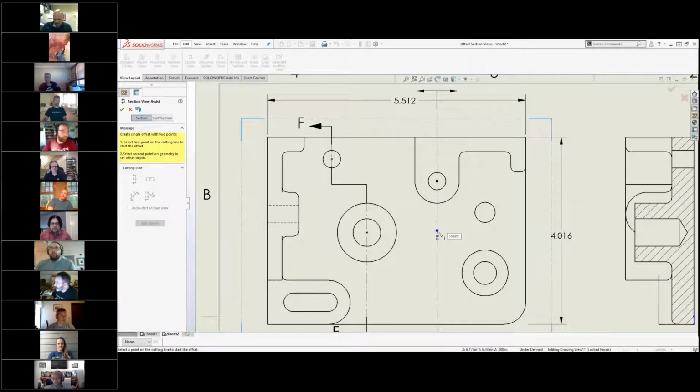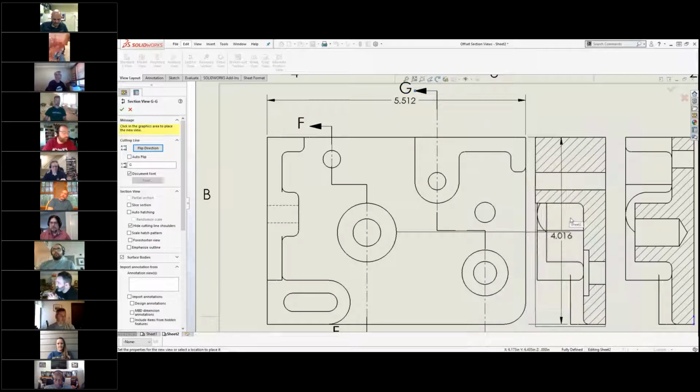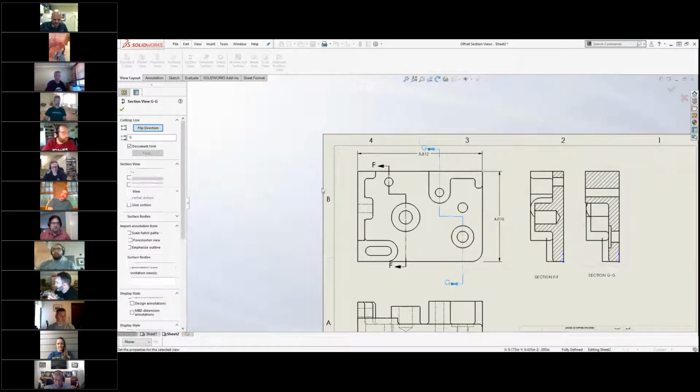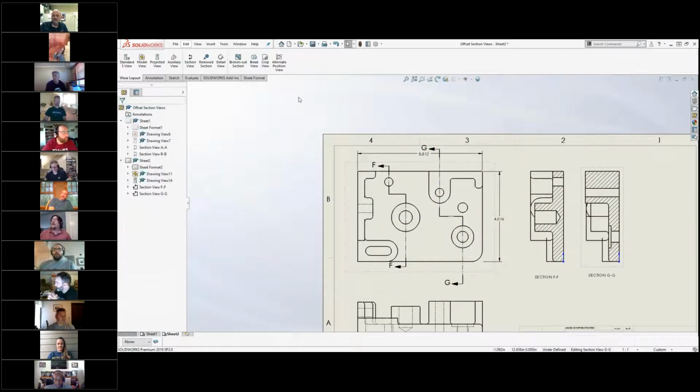So what I'm seeing with ones that are underdefined are people aren't clicking on the actual point. They're maybe just snapping to the center and letting go. They might be close, and if Eric moves around, you can see how it's white. If it's white, it's not going to add it. As soon as it turns yellow, it adds it. Because the old school ways, you had to create the points to create the relationship.